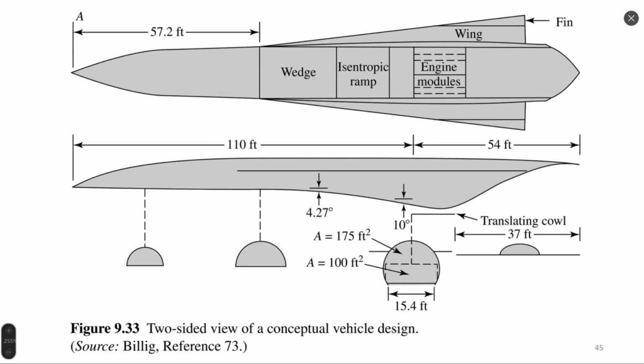There is one design. It's not new, it's quite an old design of a hypersonic vehicle, just to show you what could be a shape of a vehicle flying with supersonic velocity. There are several views. We see, first of all, a sharp leading edge, the starting point, and the trailing edge, the final point of this body, is also a sharp edge.